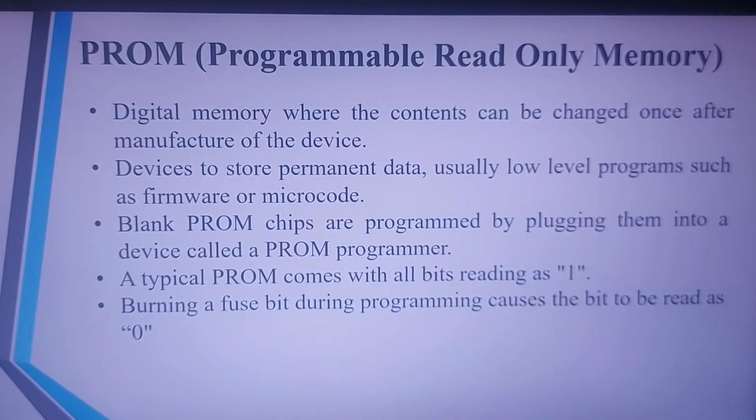If the program is not working properly, then the hardware has to be changed. That memory chip is wasted, and another memory chip has to be programmed again after modification. So before putting the program into a PROM or an OTP, we should make sure that the program is correct.